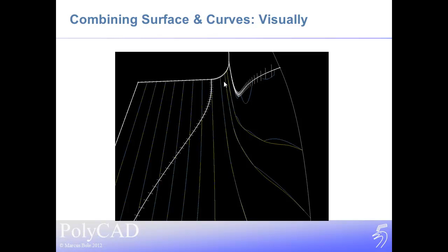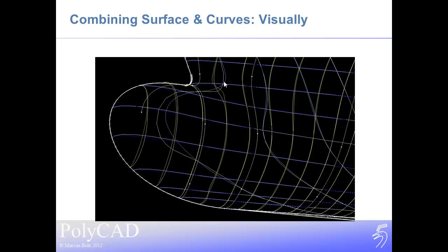So what we have here, generated from the same definition curves, is a case where these definition curves are causing some problems in the surface generation process, and we can see that in the fact that they are different from the curves that are generated from the lofting process. So having this discrepancy highlighted, we can now go into the definition and use the lofting method to smooth this out and achieve a better surface by going through that process.